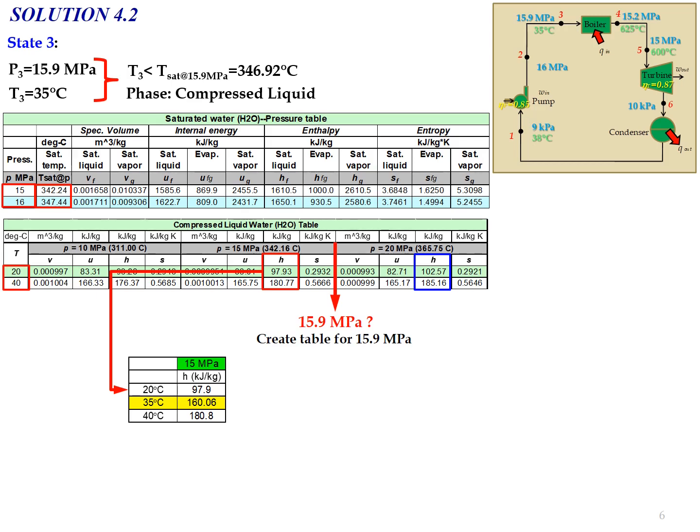We arrange the data, and obtain the value at 35 degrees Celsius by interpolation between temperature and enthalpy for 15 megapascal. So we obtain the enthalpy at 35 degrees Celsius for 15 megapascal.